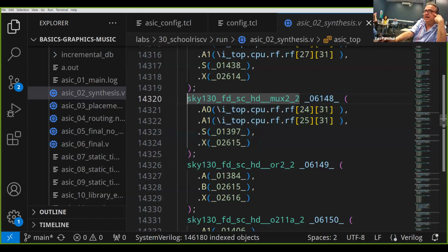And here you can see Sky130. It means an ASIC library, a library of, in the case of Sky130, 100-something types of cells which are compatible with the manufacturing process at SkyWater, a company which manufactures ASICs. So the manufacturer gives this library to a designer and to the EDA tool vendor, and the tools should be compatible with the library.